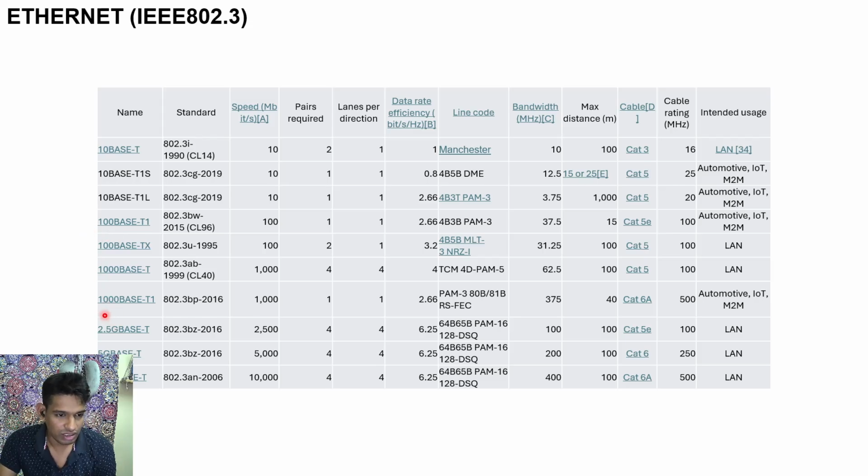And gigabit, the 2.5 Gbps, is mostly only there in your STM ports, STM16 ports. In your ULDC or telecom panel, these ports might be there, but they might not be there in your relay, or in your Ethernet switch. So these higher end ports are only available in your STM or ULDC panels, because they have considerable bandwidth. This 2.5 Gbps is, I think, if I'm correct, STM16. So these ports have different bandwidths.